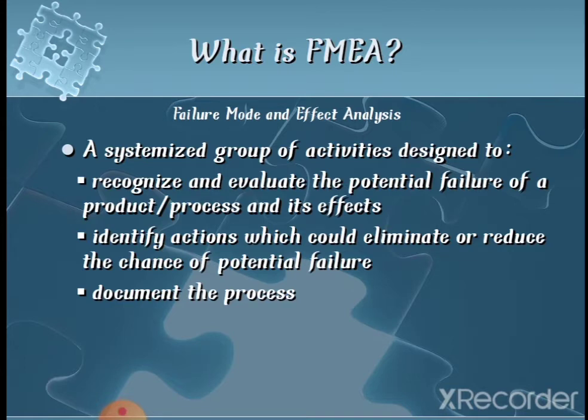What is FMEA? Failure modes and effects analysis. It is a methodology which is used to analyze all potential failure modes of various parts of a system. It is used to identify and analyze the different modes of failure of various parts in a system, and also the effects these failures may have on our system.